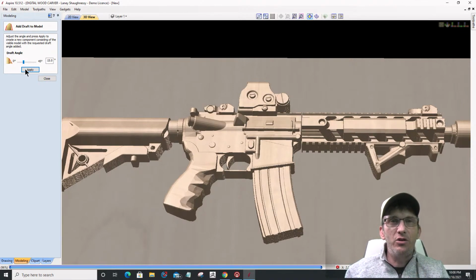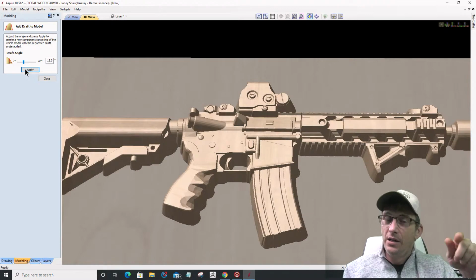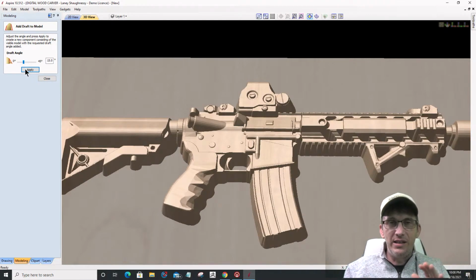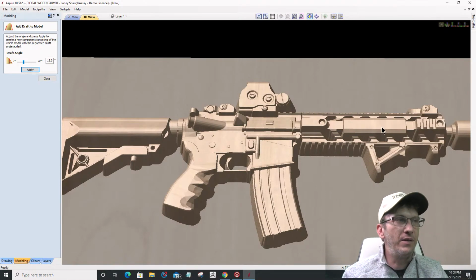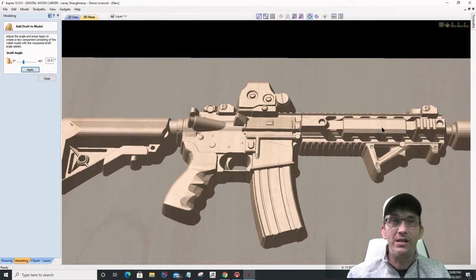If you want to optimize your toolpath and do some pocket cutting like we did before, to minimize your toolpath times, create some vectors around flat regions and areas and do a pocket cut to those regions. When you hover your mouse over a particular part, it'll tell you what that Z depth is down here, so you know how deep your pockets need to go. In my case, remember, if you're working off the bottom of your material, you do some math. My project is 1.5 inches thick.